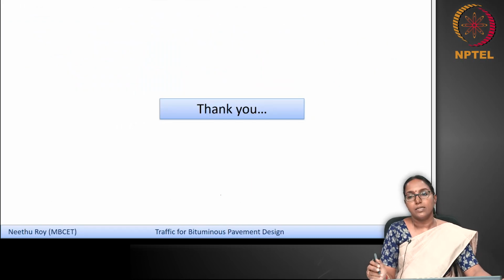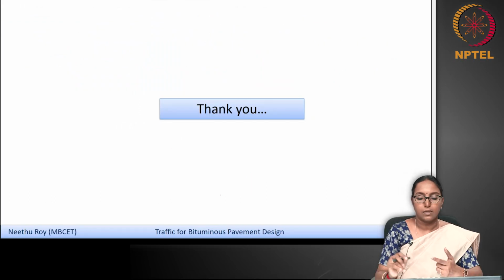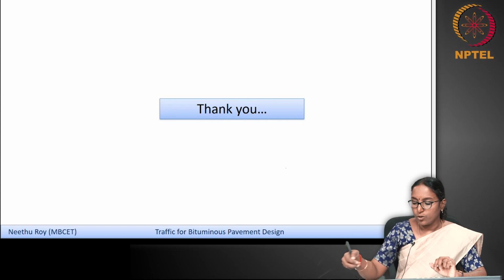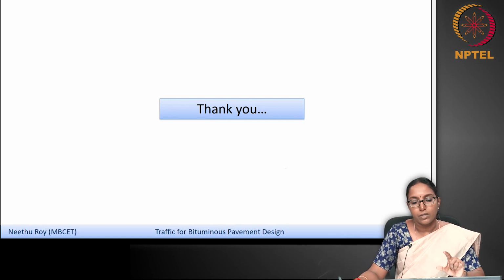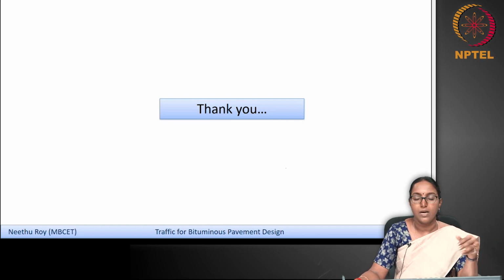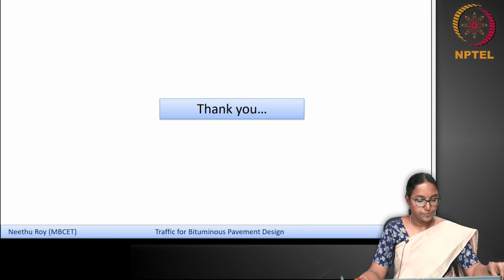So to summarize, what we have discussed in these two lectures is how to convert a dual wheel assembly into an equivalent single wheel load. We have used different criteria such as the same vertical stress, same deflection or same tensile strain with equal contact radius, and the other approach wherein the contact radius is different but the contact pressure is the same. So likewise you have converted a dual wheel assembly to an equivalent single wheel load. Thank you.